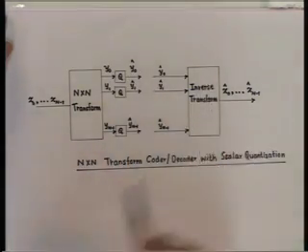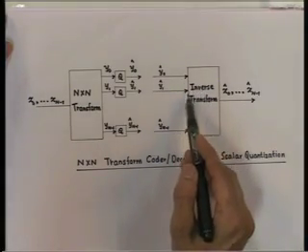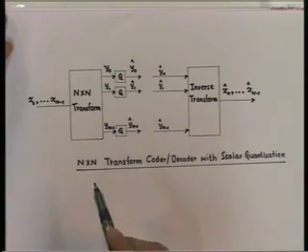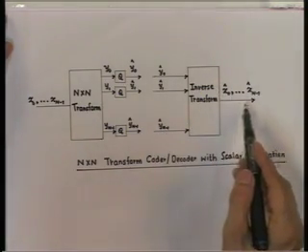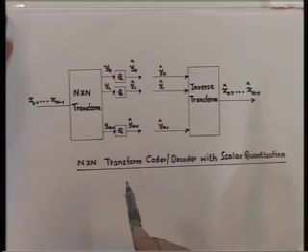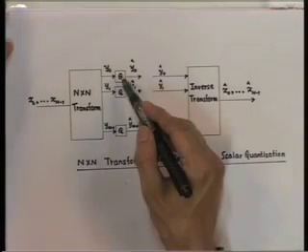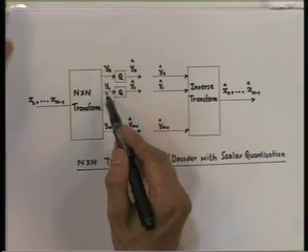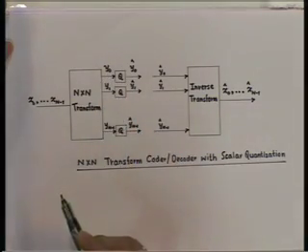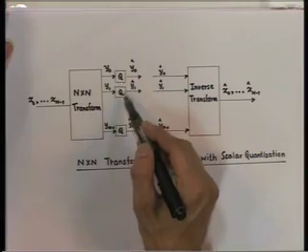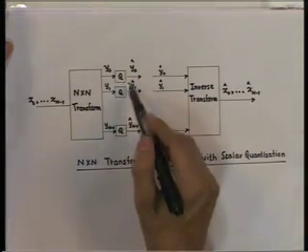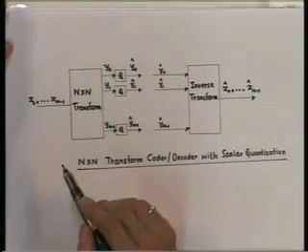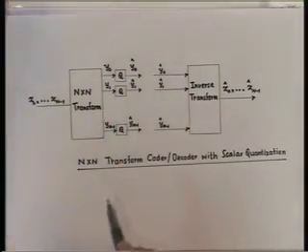At the decoder, an inverse transform is applied to the quantized coefficients, yielding a reconstruction of the original sequence. Now, by designing individual quantizers in accordance with the statistics of their inputs, it is possible to allocate bits in a more optimal manner, for example encoding the more important coefficients at a higher bit rate.